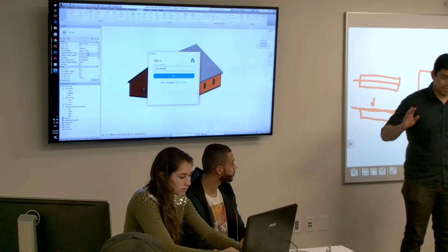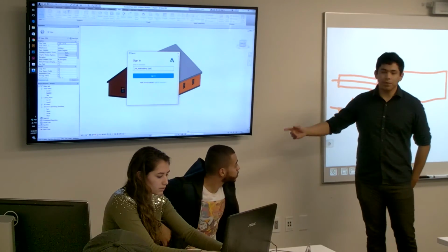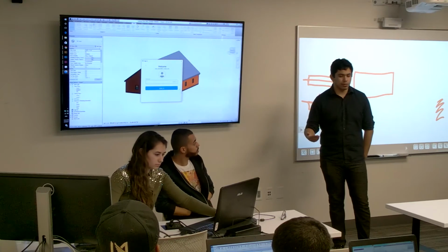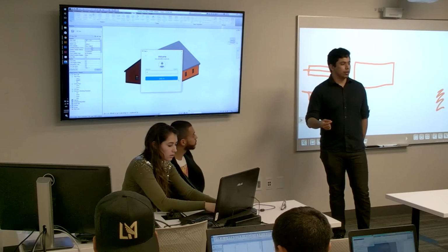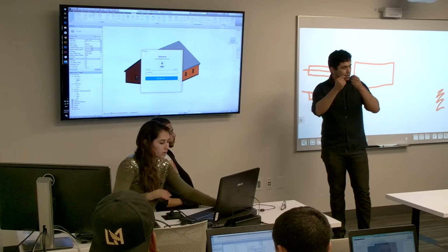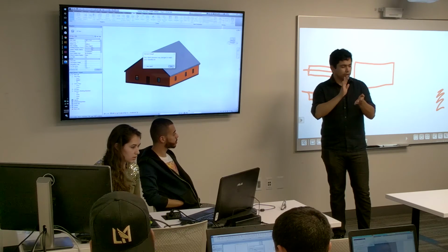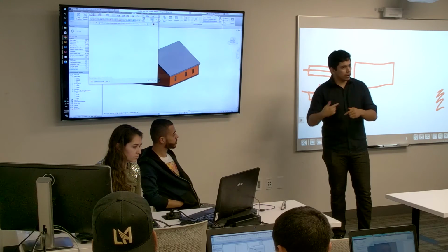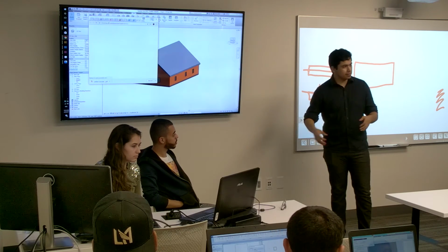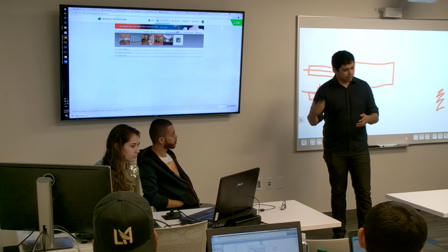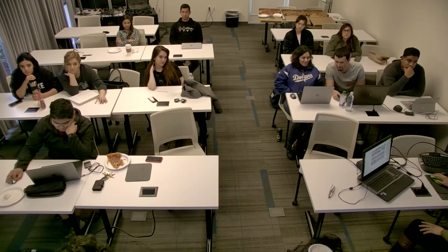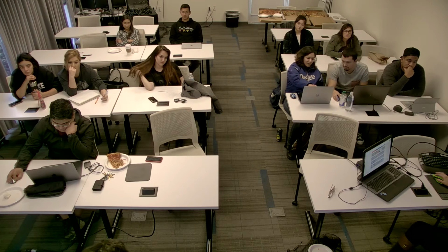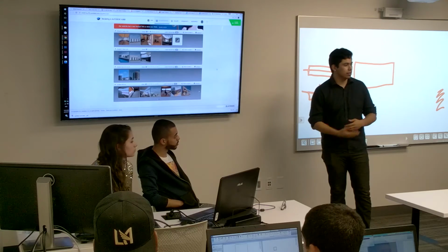While she's signing in, just as an aside, that render view, if you keep it on low, I use it every single time that I'm working on this because one, it doesn't wear out your computer, and second, it's always a good idea. It keeps you in reality. Let's say one material just doesn't look right, you can always not export it and just change it and then render it again in low. Look at it. If you like it, export it. If not, exit out again. And you can continuously do this as much as you want, which is good for different iterations, or if you just want to have different variables.